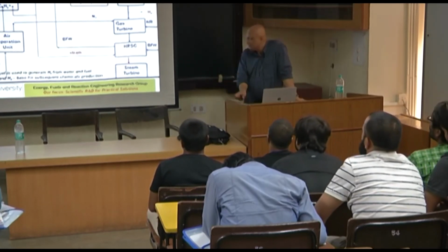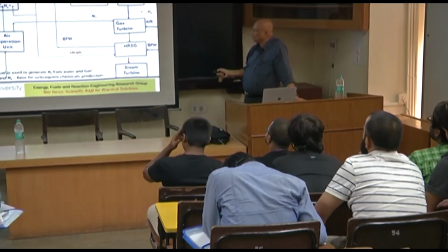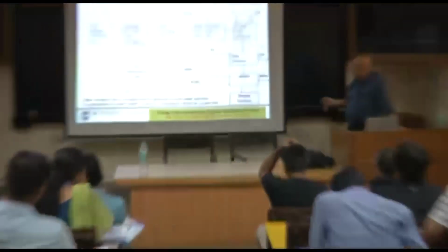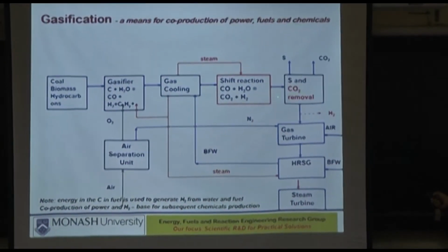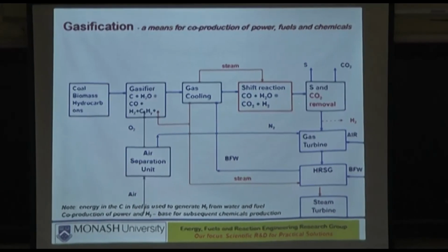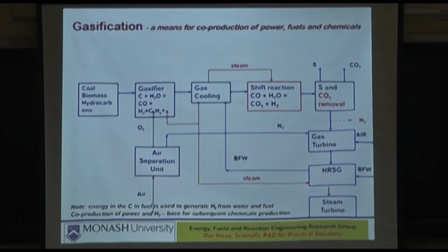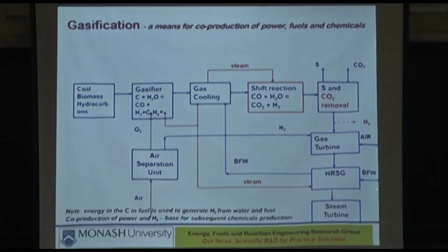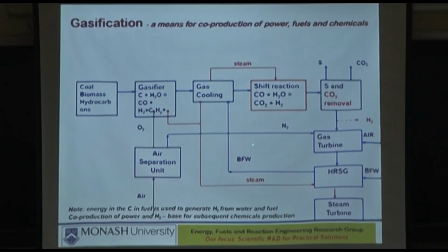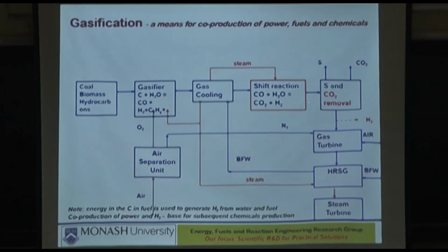Yeah, in this instance, in the scheme that I have shown, it is not quite external, because we have to cool the gas. By cooling the gas, we are generating the steam. Some of that steam can go into the system. So, externally, what you are providing is only the boiler feed water. In that sense it is external water, but the steam is generated internally. Correct.